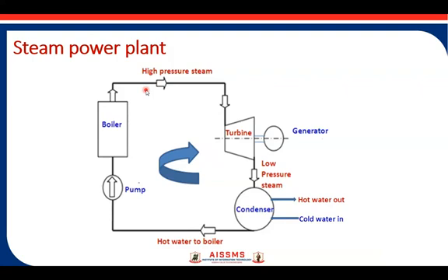Steam power plant can respond rapidly to the changing loads without difficulty. The portion of steam generated can be used as process steam in different industries as well. It can be located conveniently near the load center, that means near to the application. It can be set into the industrial zone or application zone so that we can reduce the transmission cost and efficiency can be increased.